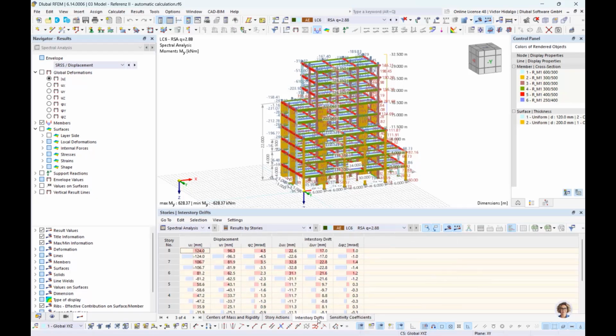For inter-story drift, just as an example, if I show this with the subresult SRSS, this would not be the real result. These are smaller displacements. These are the reduced displacements, and the subresult displacement would be the true result for this table. But this is quite the same for all standards.